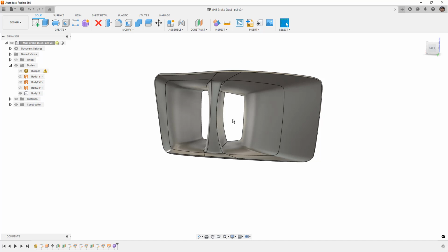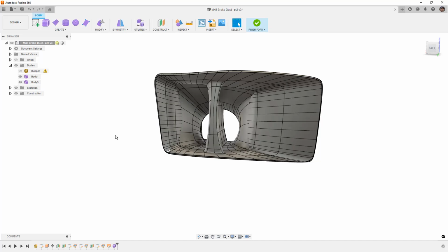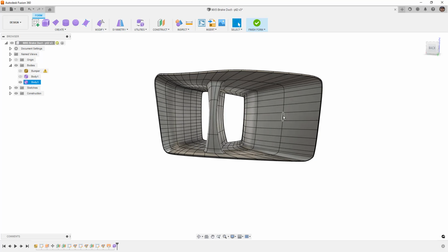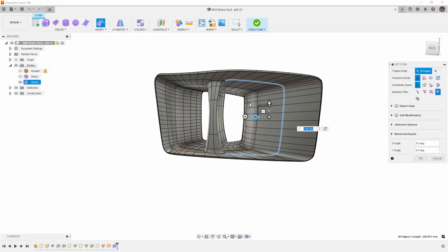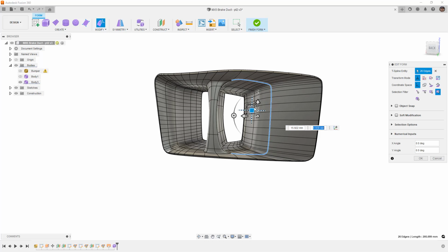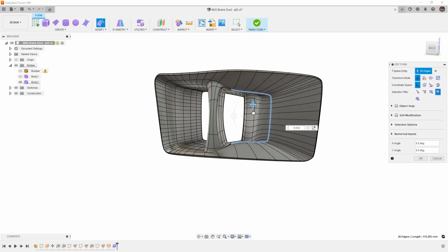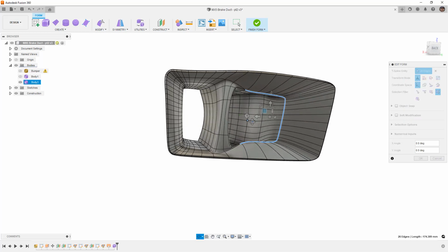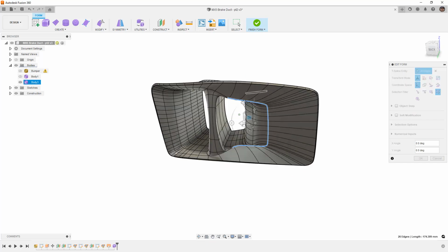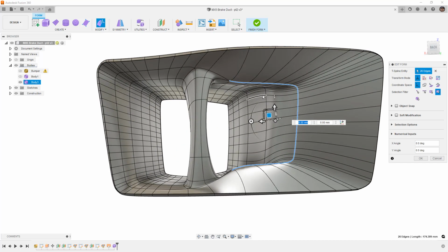Doing this with Thicken, once you get the basic shape down, can be a handy way to add some complexity to your design. But once again, it does really ramp up the difficulty you have in working with these types of models. Once you have to add this many divisions to continue working with it, it becomes quite the chore when you're trying to model in this manner. So for example, as I start to move things around and scale them down, I now have to consider not only the shape that I'm working with, but also the fact that I might be overlapping the outside and not able to convert the shapes.